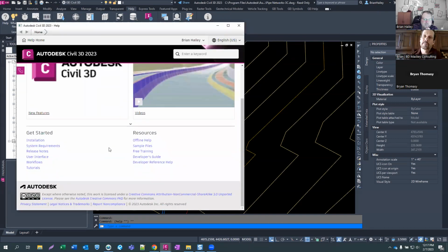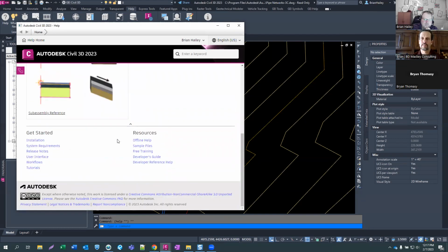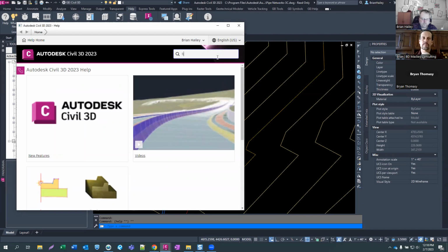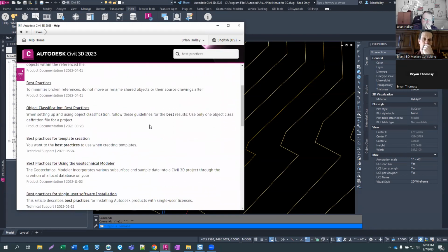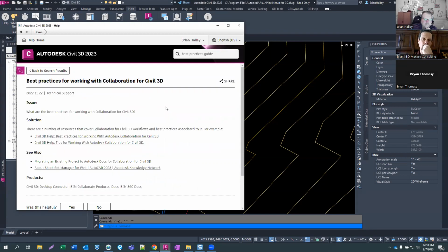Within my company, we work with individuals that don't have Civil 3D. So we've got AutoCAD users, Civil 3D users, Plant 3D users. To enable them to XREF in the surfaces and the contours and data like that, since they don't have the ability to data reference, we'll create a model file that is just the data reference of just the surface.